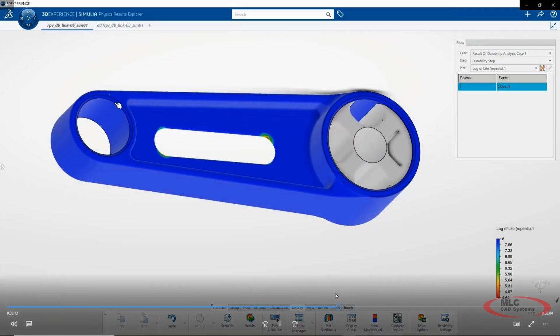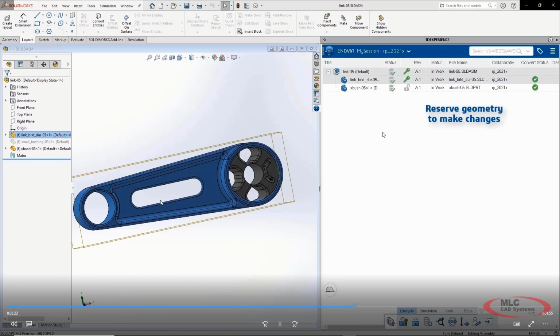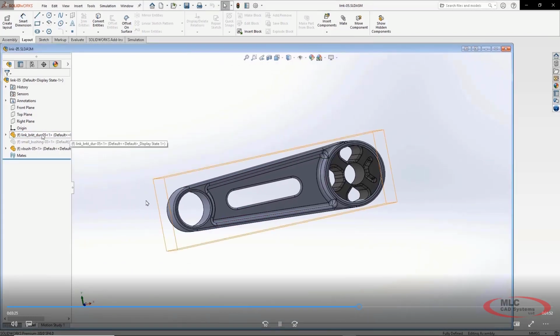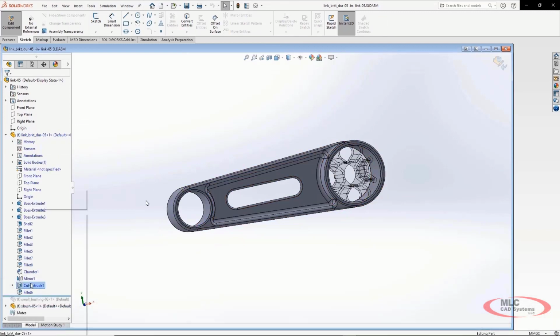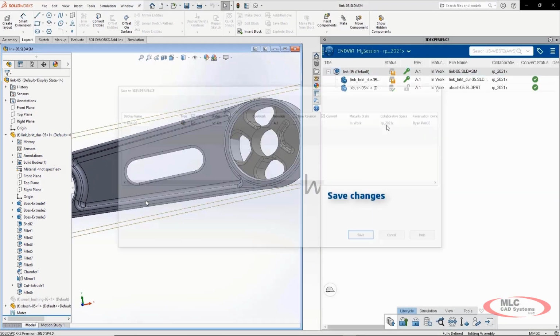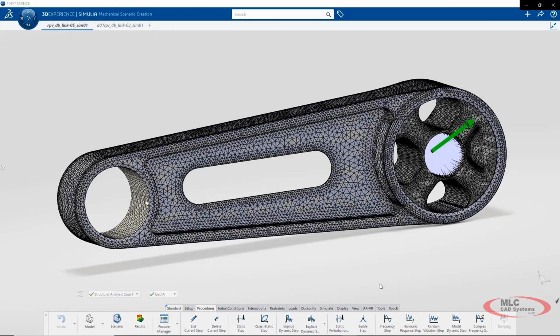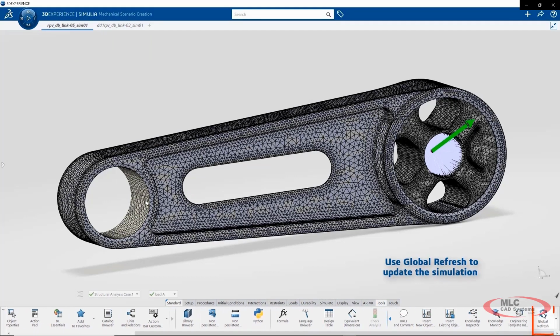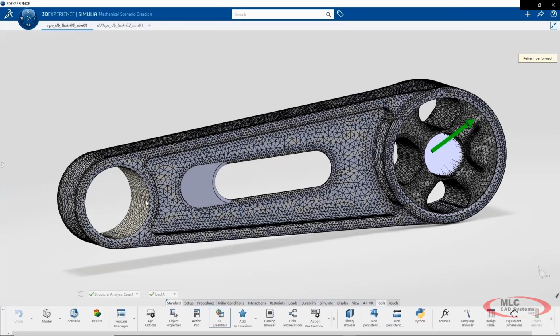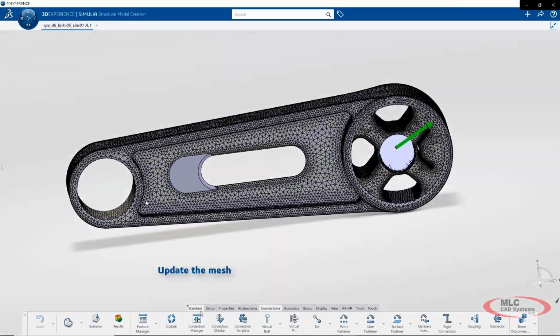So in this case, here in a second, we'll go back into the SolidWorks environment, and we change that bracket to have a slightly smaller hole in order to meet our design requirements. And we'll see, we change the size, and we just go back to this connector and tell it we're ready to transfer these design changes over. And then you go back into the simulation environment and say, I'm going to update my geometry, and you just tell it to remesh and rerun, and you're good to go.